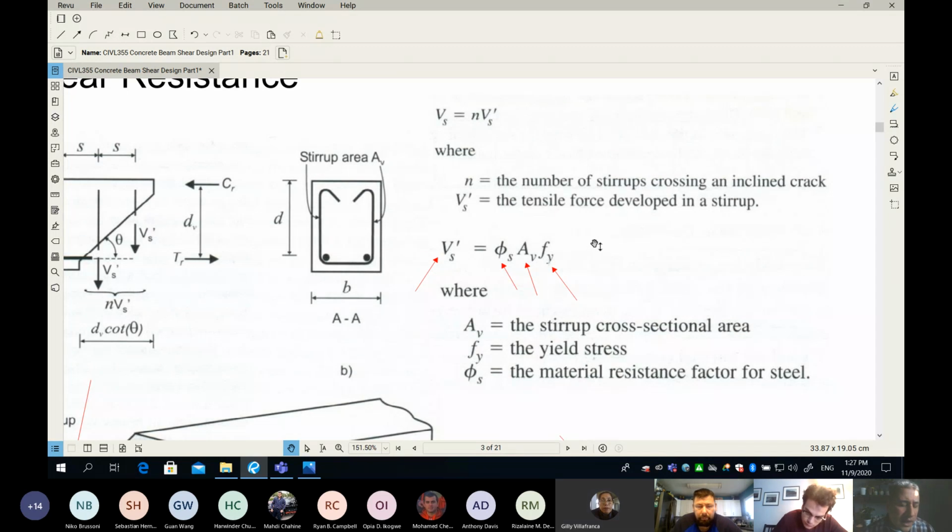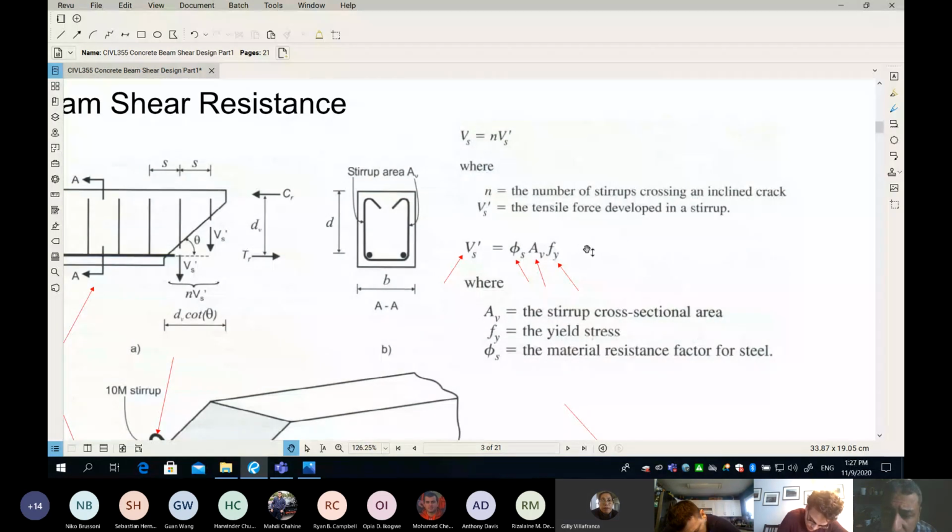Yes. Okay. Listen, so far the idea is super easy, but the question is, what is Av? Please be patient with Av. Av is the area of a single stirrup, and I'll give you more details in a few minutes. So for now, this is the area of a single stirrup. Multiplied by the reduced stress, it means I get the force that will fail a single stirrup.